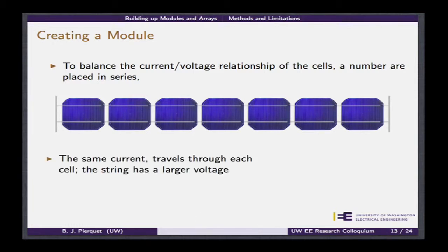So in this case, we get the same amount of current through each. It's just a series connection. There's no other place for current to go but through each one. And so in this case, essentially all you're doing is summing up the additional voltages. So the currents are constant. And so if you generate the new IV curve, you will have the exact same current profiles. All that's going to happen is your voltage range is going to stretch out.